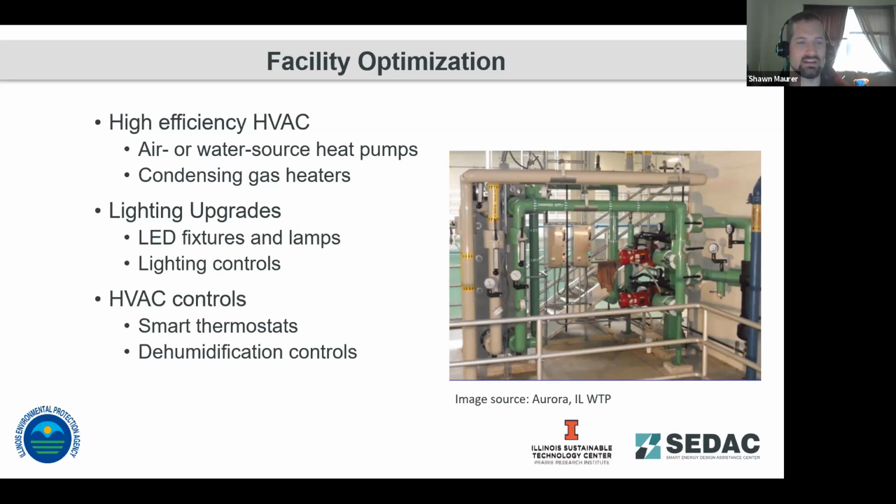And we also look at lighting controls like occupancy sensors and timer switches. For outdoor lighting, a lot of what we see is new fixtures, particularly LED fixtures that have been upgraded, have individual daylight sensors on them. And those daylight sensors tend to fail relatively quickly, and then the outdoor lights are on even in daylight. So we look at optimizing those to either a centralized daylight sensor, so you've only got one to maintain, or tying those to a time switch or a manual switch, so those lights are only on if someone's there at night, or if there's a safety reason to keep those lights on.